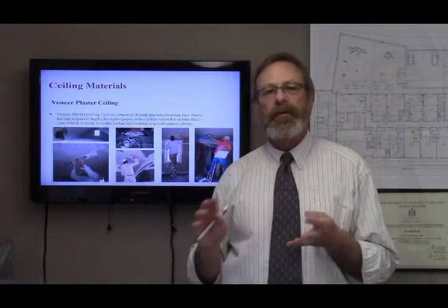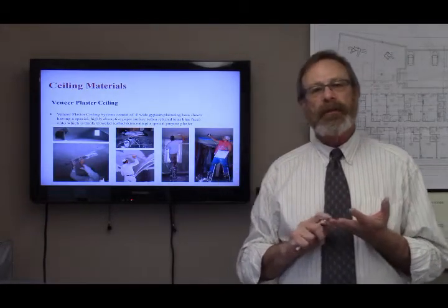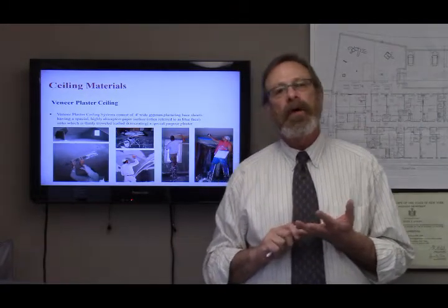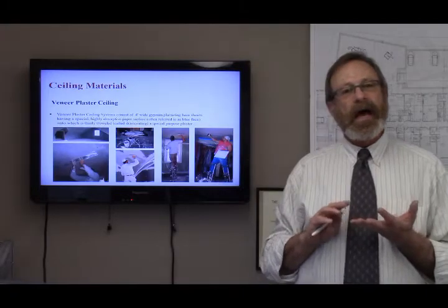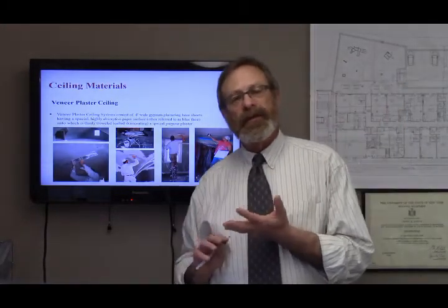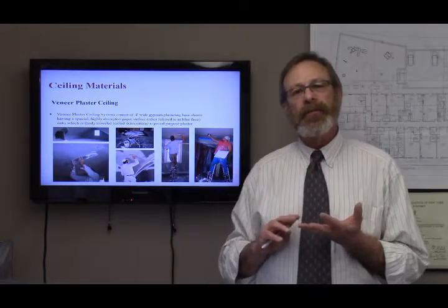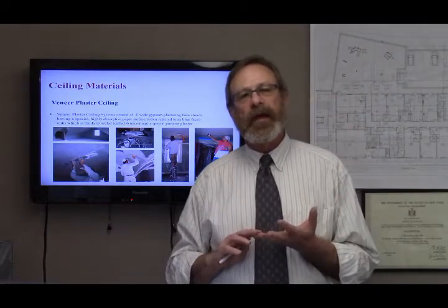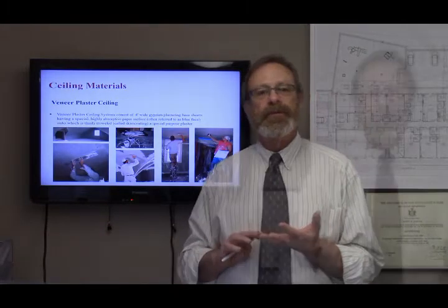We now have spoken about gypsum wallboard ceilings, GWB ceilings. We've talked about full plaster ceiling systems, and just like when we spoke about walls, we have an intermediate methodology, not as expensive as full plaster, but a superior finish from gypsum wallboard. It's called veneer plaster ceiling systems, and the advantages are the same as we spoke about when we spoke about veneer plaster wall systems.